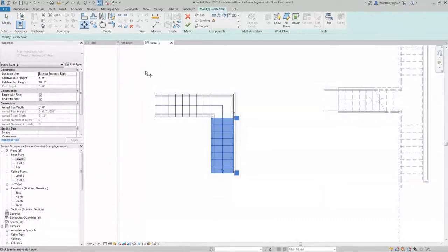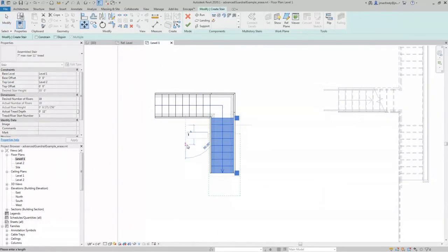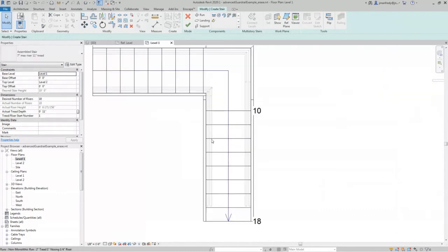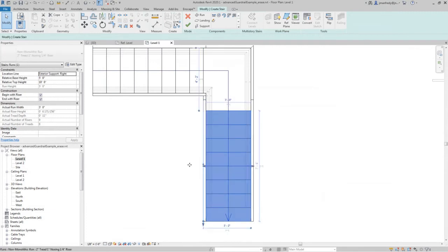Now let's say I move it down a foot to show you what happens. One foot. So the landing got longer, and what we're trying to do is get this handrail to come down, down, down, hit a place where it becomes horizontal, meets this member coming up here horizontally before it starts making a nosedive toward the bottom of the stair. So I'm trying to find that sweet spot. I move this down a foot as an example.